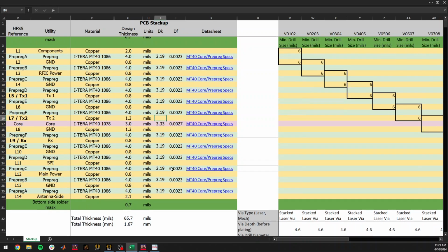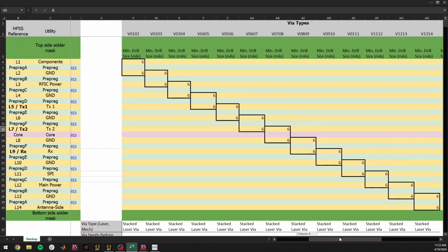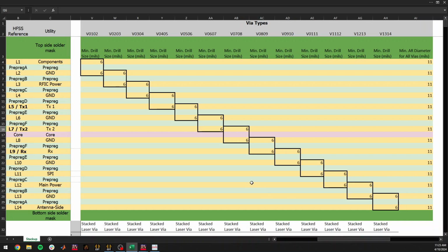material. And one other thing to pay special attention to, especially in mmWave designs, is the types of vias that you're able to use. In this case, we're using what's called a microvia, or every layer interconnect, or ELIC technology.